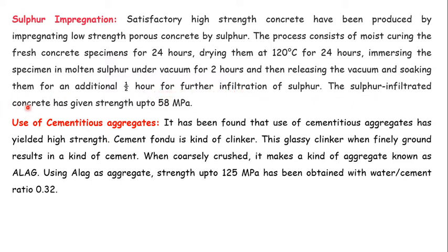The sulfur infiltrated concrete has given strength up to 58 megapascal. So sulfur impregnation means high strength concrete can be produced from low strength porous concrete by sulfur. So we are going to provide a small amount of sulfur into that.